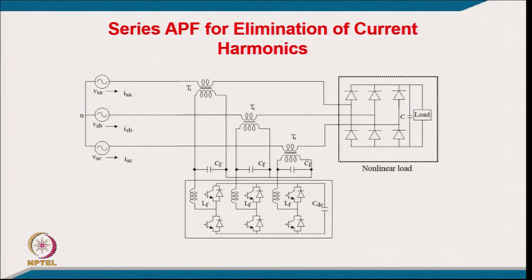Another function is the series active power filter for elimination of current harmonics, and you can see here a 3-phase series active filter with an injection transformer. I was mentioning that it can eliminate the harmonic currents of a voltage fed kind of load. So, this is our diode rectifier with a capacitive filter, which is a voltage fed load, and here we have another parallel load, maybe you can call it an inverter fed 3-phase induction motor, or even a brushless DC motor or PMSM after this inverter.